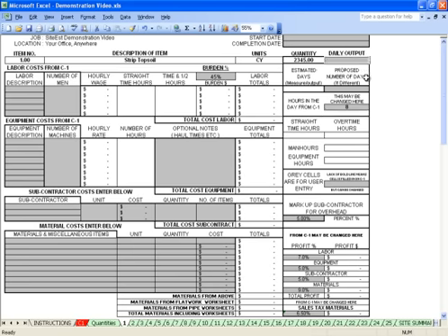With a D6 dozer, I'm going to push 650 cubic yards a day. That shows me that I can do that in 3.6 days. Let's override that and say 4 days. And what I'd like to do is change my 8-hour day to a 9-hour day.